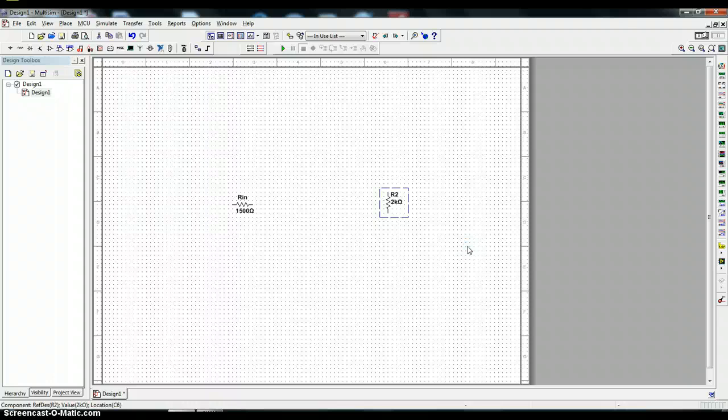You can hit Control R again, and it turns back around that way, and hit it again, it comes back vertically. You can keep doing Control R and rotate it 90 degrees each time. There is no Control left. You really don't need it in a way because you can actually just do 3 Control R's for a component. You wouldn't have to do that with a resistor.